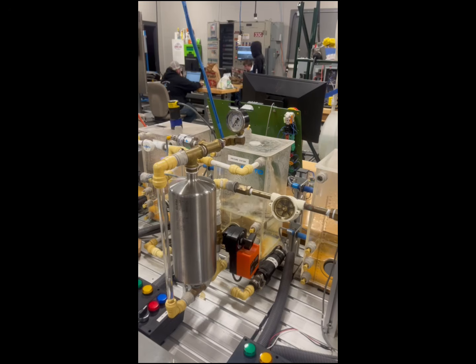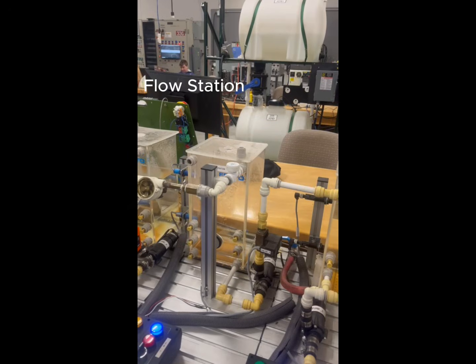In the pressure station, the tank will fill up to a good level, and once it does, the water will get sent to the pressure tank, where the process will try and reach the desired pressure set point by automatically opening or closing the analog valve with a PID loop. Next is the flow station, where there is a flow meter counting the milliliters per second of product coming from the pressure station.